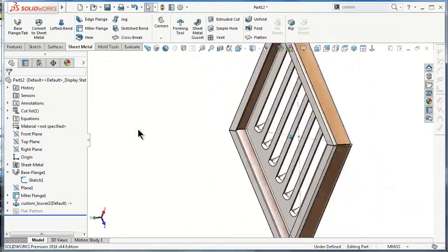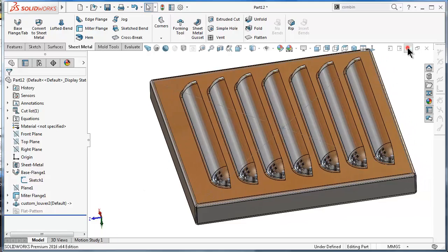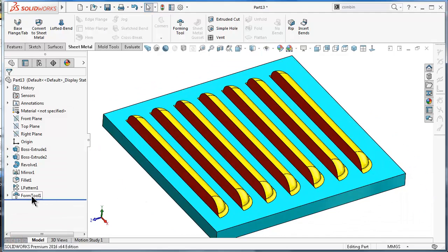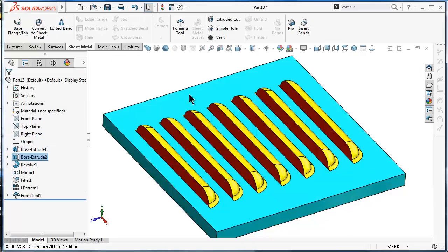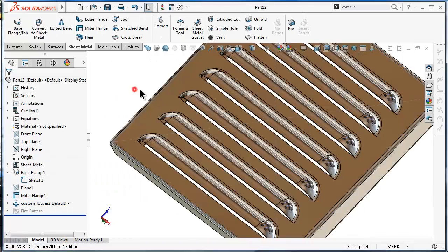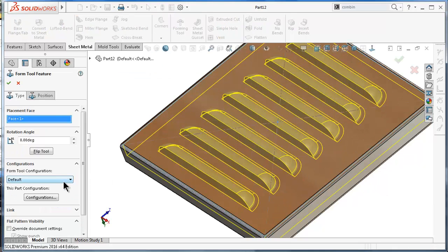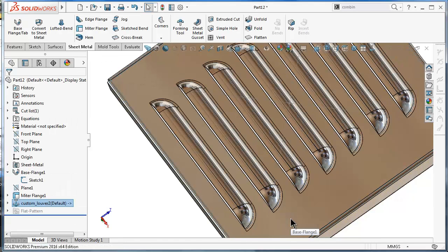So that means these louvers are linked to the main die. So any change you make here will be changed as well on the grill. So let's edit the length of this grill, make it 75. Click OK. And here you don't see any changes. To see the changes, go to edit feature and return back. You will see the sketch is updated.